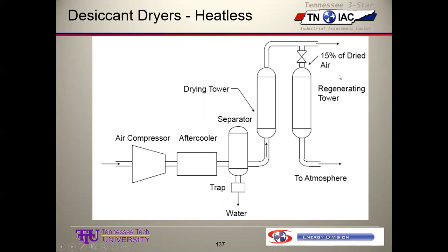150 CFM. Well, let's say we're operating at 20 kW per 100, and I've got 150, so that's 30 kW of compressor power that I'm spending to regenerate that dryer, times, let's say 7,000 hours a year, because there are some times when it maybe doesn't bleed all the time, times, if it's 8-cent power, that's almost $17,000 in compressor energy that we're wasting on regenerating. So we're running a 200 horsepower compressor, which would get us 1,000 CFM, but I only got 850 to put out to my plant because I'm bleeding 150 through this dryer pretty much all the time.